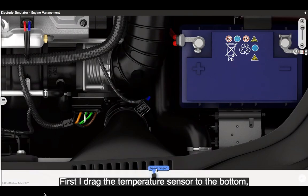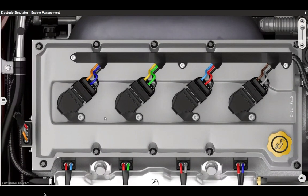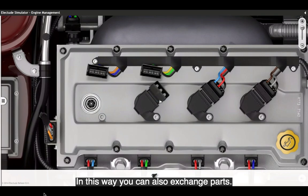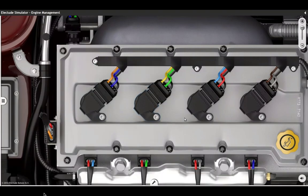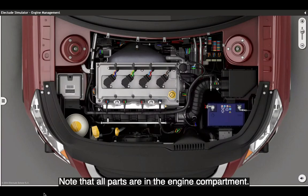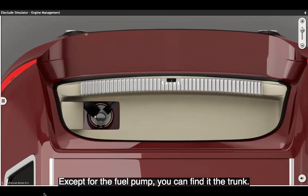First, I drag the temperature sensor to the bottom. Then I replace it and put the sensor back in. In this way, you can also exchange parts. For example, now I exchange 2 ignition coils. Note that all parts are in the engine compartment, except for the fuel pump, you can find it in the trunk.